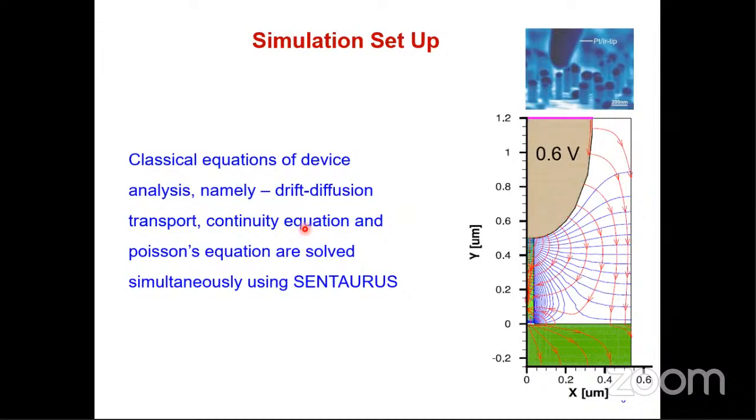Dou n by dt is equal to 1 by q, the change in current density with respect to the distance, minus the recombination of electrons plus the generation. Correct. So good. So you have two continuity equations, one for holes and one for electrons.